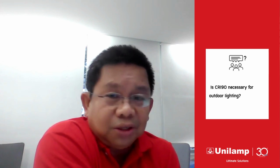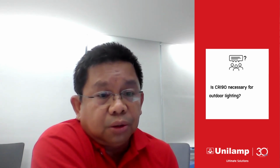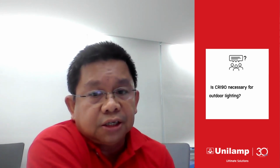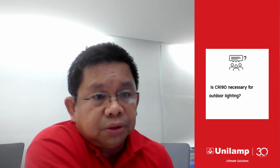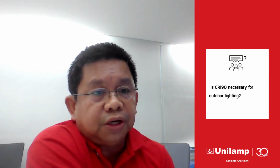Is CRI 90 necessary for outdoor lighting? If you ask me, is all this marketing? Outdoors, probably 80 plus, 80% plus, is already acceptable. CRI 90 is probably more necessary in indoor applications, for example when you want to highlight merchandise, or you are in a museum where you need a bright color for a certain object.